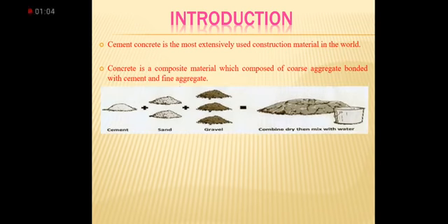Here we are trying to show a ratio. A pan of cement, 2 pans of sand and 3 pans of gravel. It means we have a ratio of 1:2:3: 1 cement, 2 sand and 3 aggregate. When it is thoroughly mixed together with water, it becomes concrete.